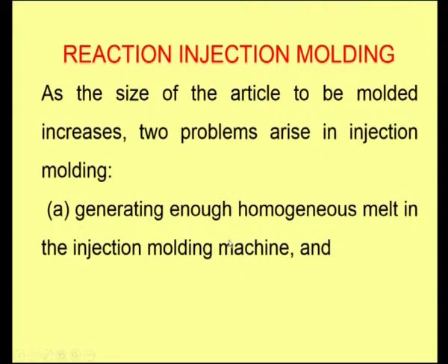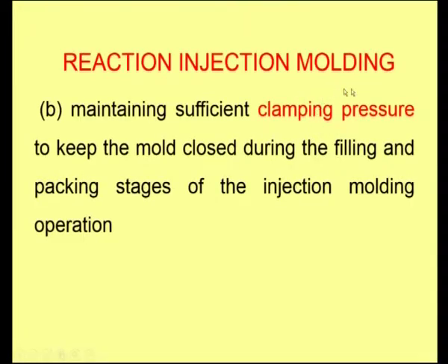As the product size becomes larger and larger, then you need to melt more and more resin in the single screw extruder. So, therefore, the barrel size is going to increase, and correspondingly the heater elements that are required will increase. So, that will ultimately increase the cost, and not only that, the increase in temperature would also affect the rheological properties of the polymeric melts. So, therefore, this is one of the serious issues with respect to the size of the product in injection molding.